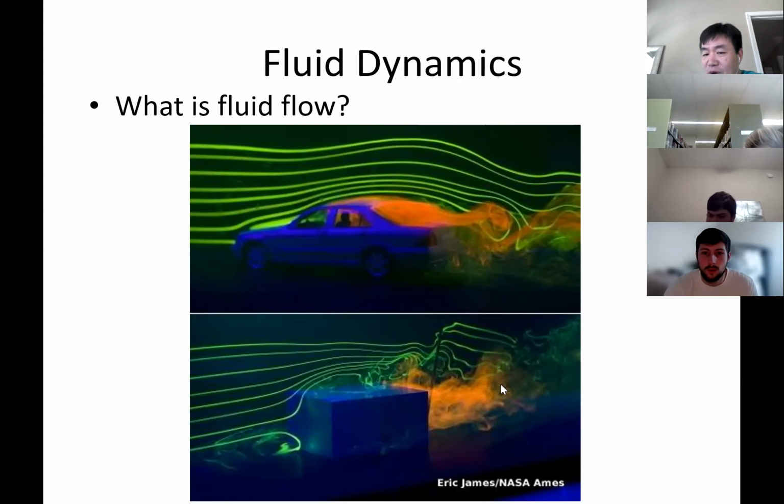The lower the pressure in the back, the bigger the drag is, because drag is calculated from the pressure difference between the front and the back. If both cases have similar front pressure, then the lower the wake pressure is, the bigger the drag is. Okay, the worse the performance is in terms of the race car.